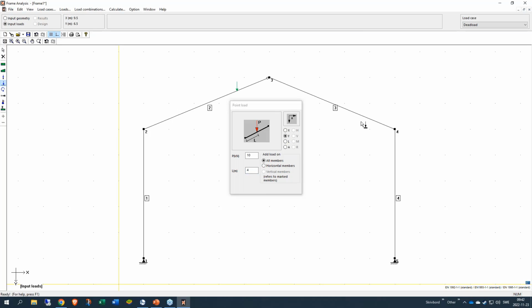On the other element, I defined it from 3 to 4. So that would mean that the point load would be down here. So instead I will use 1.4 and apply it to get it up here. If you want to define a point moment on an element, it is possible to enter the value and also the length from the starting node.